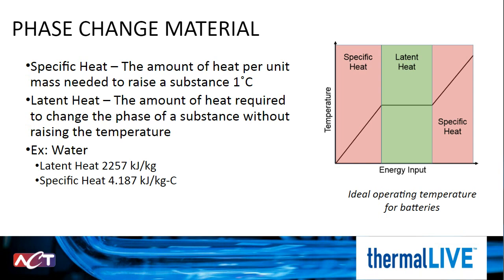It also would require storage in a subambient garage for hot climates and storage in an above ambient garage for cool climates. It would essentially be charging the PCM before use, just like you're charging your battery. So if you're going to be in a hot environment, you'd want your PCM to be frozen or cooled before use. And in that cold environment, you'd want your PCM to be hot so it can heat up your battery before use. While it has benefits in the short durations and moderate climates, the long-term feasibility of a PCM solution for EV operation is questionable.